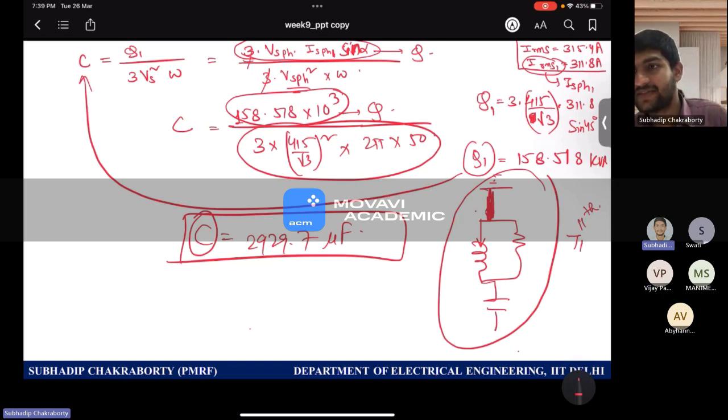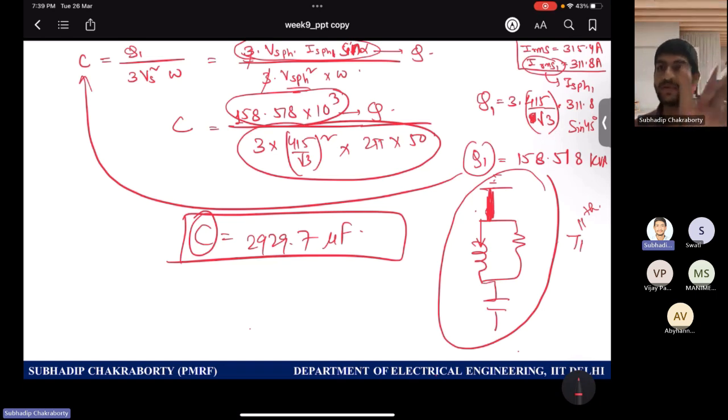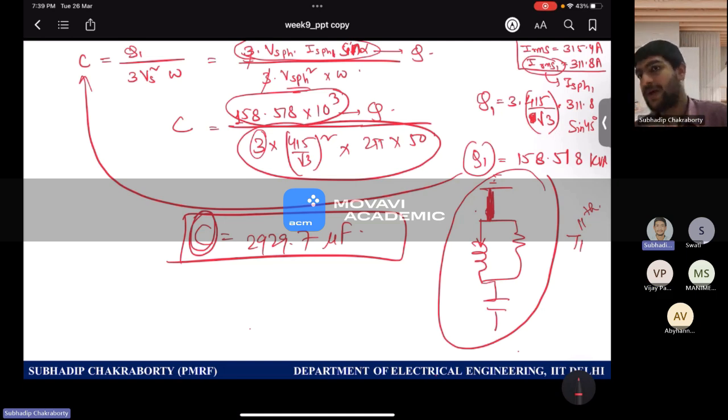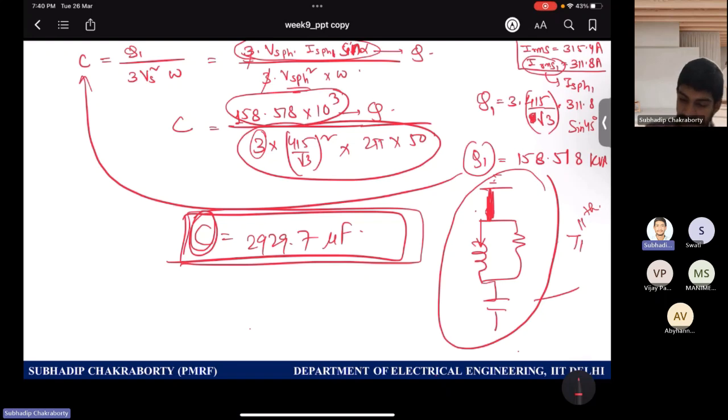We divided actually by 3, because per phase we have 3 layers which are contributing to the reactive power, because capacitors we are assuming same value, but here only one single layer. So capacitance value per phase we determined by 3, but no more by 3, because in per phase we are having only one capacitor sitting there. So that is the absolute value of the capacitor. So this is the arrangement. So the language is important.